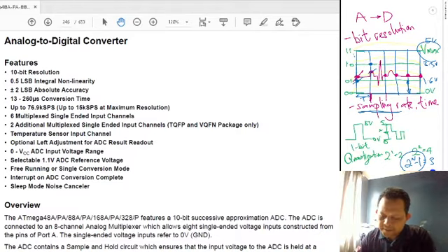Okay, so the next point will go to the nearest voltage level, which is 1.6, and also the next 1.6, and then again 1.6 and 1.6. So what your microprocessor will store after the ADC conversion are these values. The first one is 01, the second one is 10, right? And then the third one is 01 again, and then 01 and 01 and 01.